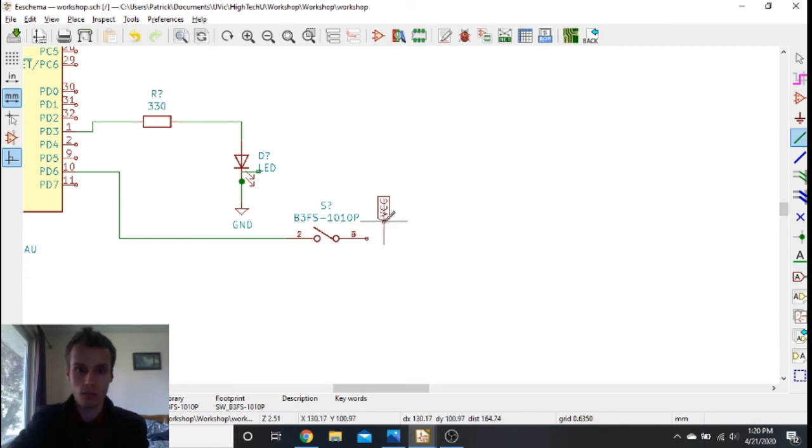Connect a wire, but there's something we should remember. There's a concept for resistors called pull-down resistors. The goal of checking for this input is that it's at 0 normally, and then it's pulled to 5 volts when this button's being pressed. But how we currently have it, the value going into the input when the button's not pressed is undefined, which doesn't always have to be a problem, but it's not good to leave it like that.